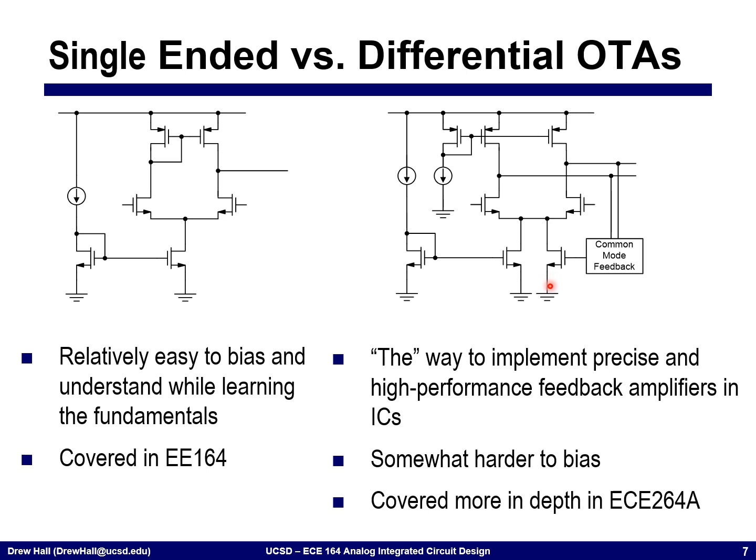And oftentimes what you're going to find is that there's a little bit of mismatch. We talked about process variation in a previous lecture and showed that even if I make two transistors nominally right next to each other, based on their area, there's going to be some variation between these two transistors. It's not such a big deal for this differential pair.